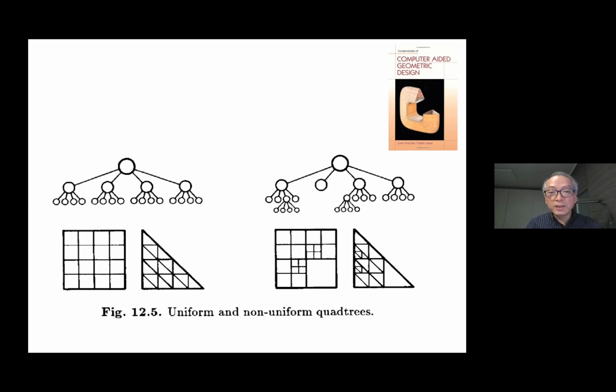And then conventionally, in CAD, we consider the convex hull of control points the main convex bounding volume for the surface, or sometimes AABB was used. But we can have a large variety of other bounding volumes for the nodes around the root node, or for leaf nodes, we can use some other things. So in our recent research result, we used osculating toroidal patches for those leaf nodes. That's the basic difference from the previous approaches.